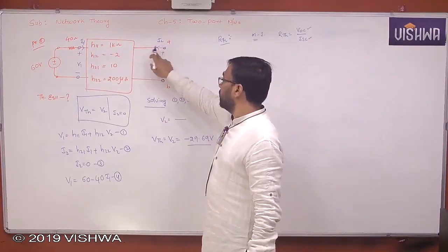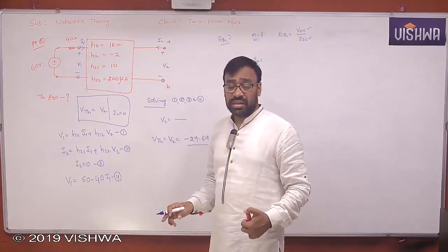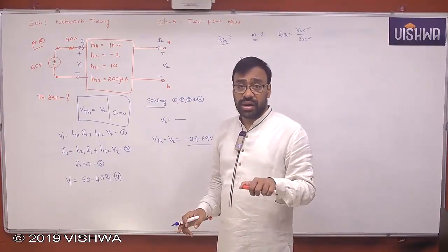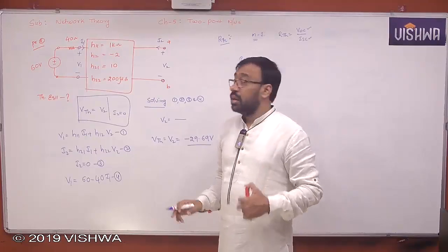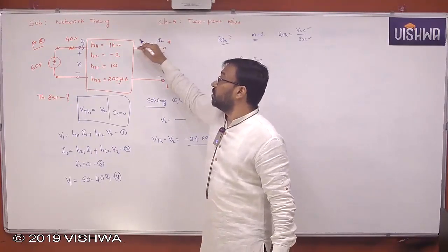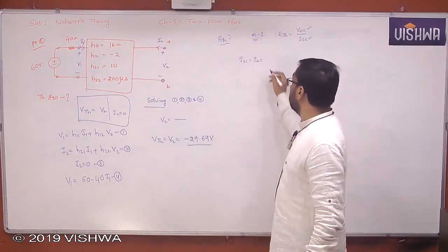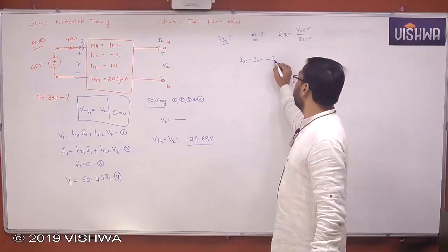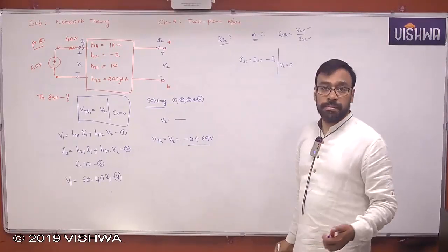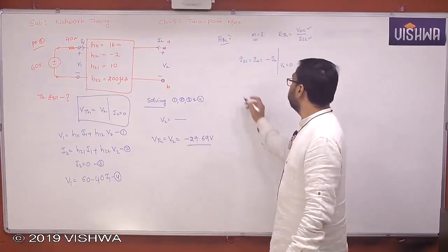But I2 flows in this direction. ISC is required in this direction. The load draws the current, right? Norton's current is nothing but load current. But the load draws the current, so the current flows in this direction. But in our two-port network representation, the variable is shown in the opposite direction to the load current direction. Therefore, you must take it as minus I2. But under the condition V2 = 0. That's it. Okay.